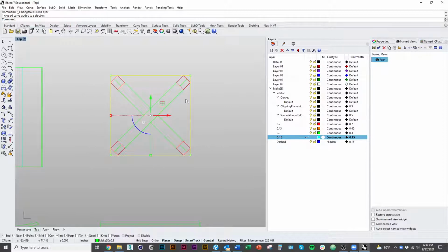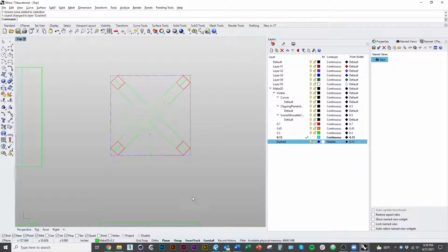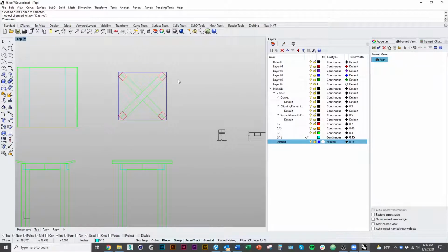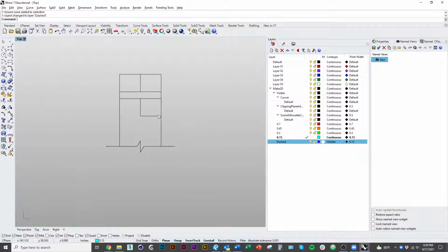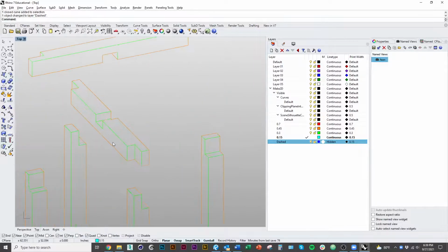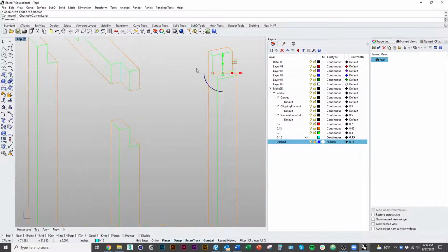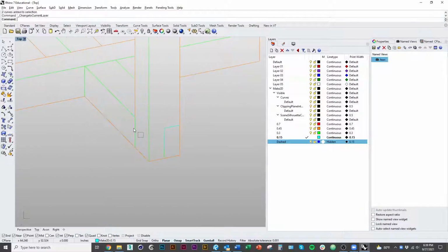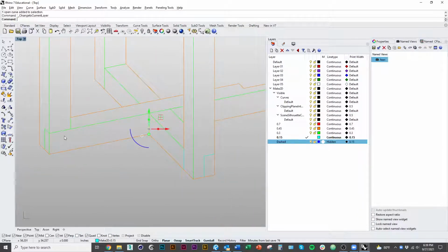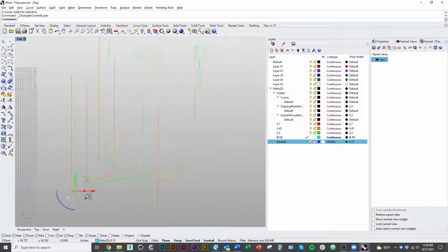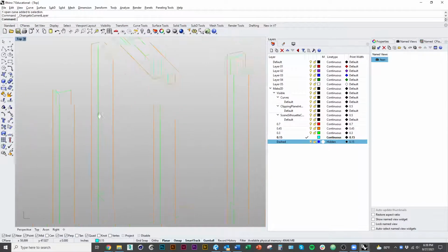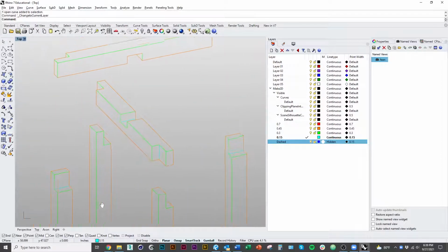So this is the outside outline of our dimensions. We might want to keep that just so we can show what the size is, but I'll put it on a dashed line to show it's not really geometry or anything. And then actually you could do the same thing with line weights here. Receding lines should be lighter, right? Receding corners, protruding corners, of which there's fortunately not that many. Pretty good. Okay.